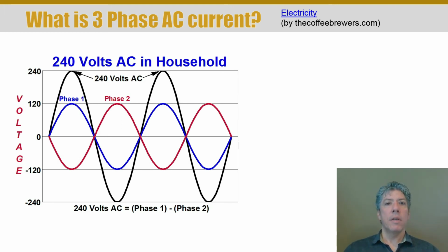But sometimes something kind of interesting happens, and it seems a little more, I guess, paranormal or confusing. At least it was to me. It happened a couple of times when I was asleep, and I got up and I'd turn on one light switch and it wouldn't do anything, and I'd go into another room, turn that light switch on, and it worked fine. And I was like, what on earth is going on here? This is very strange. Well, what had happened was one phase leg was out, and so things that required two phases, for example, my air conditioner, it didn't work right.